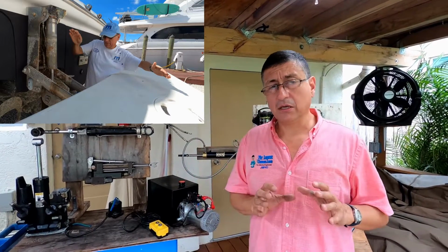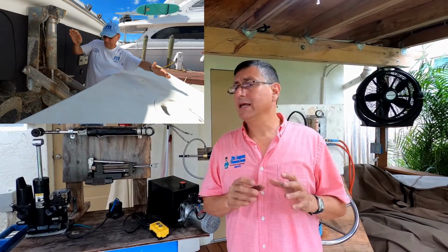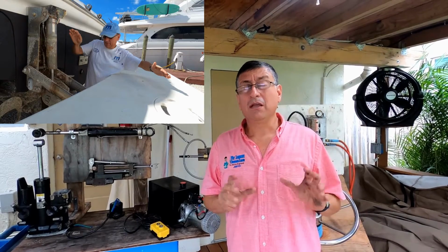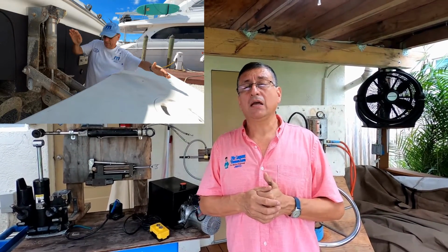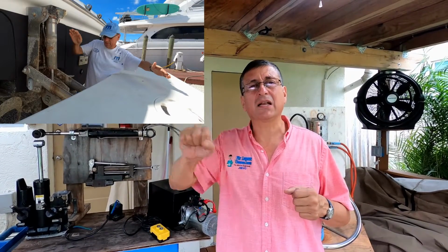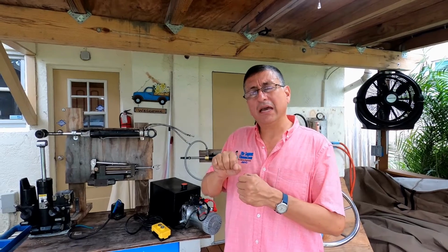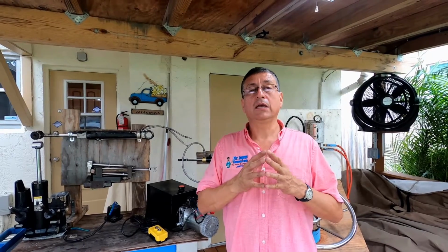When the oil is mixed with the water, there are a lot of inconveniences. Immediately the temperature of the oil increases dramatically, and some motors, some actuators work erratically and intermittently, not constant, no soft movement. This is an indicator that the oil is milky.